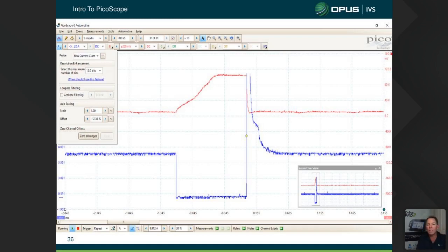So what I can do is scale the pictures I'm looking at. I can reduce my ignition waveform, bring it to scale. We don't change the shape or the size of the pattern. It's just its scale that reduces. And that's simply so we can fit it on the screen and compare it to other patterns, so we can look at ignition versus fueling at the same time.